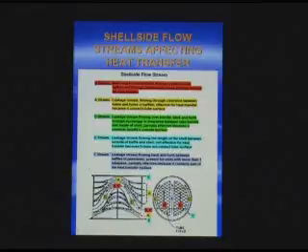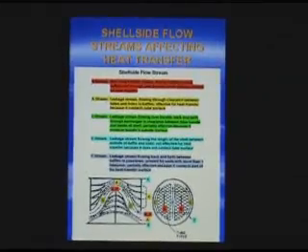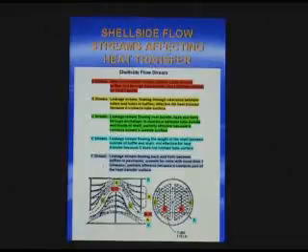Generally for sizing an exchanger, we would like to have the window velocity through the baffle about equal to the crossflow velocity. If you have a very high window velocity and a low crossflow velocity through the bundle, you might enhance leakage streams and not have the optimum A stream. We'll have an animation a little bit later on which will kind of clarify that. So that's for general information.